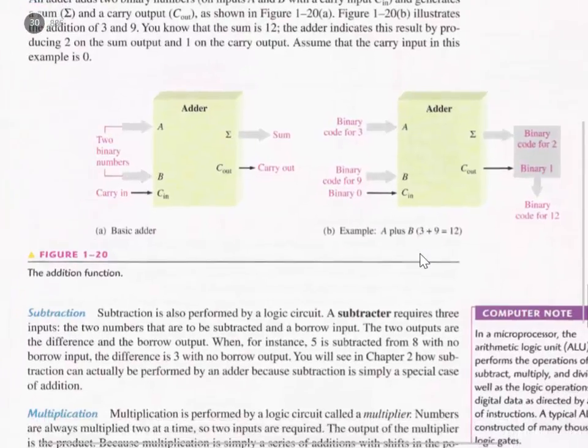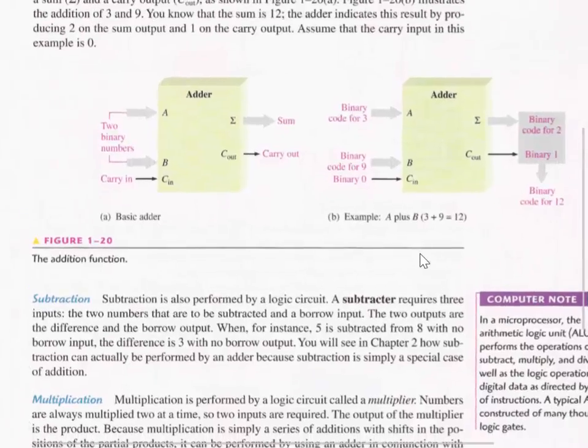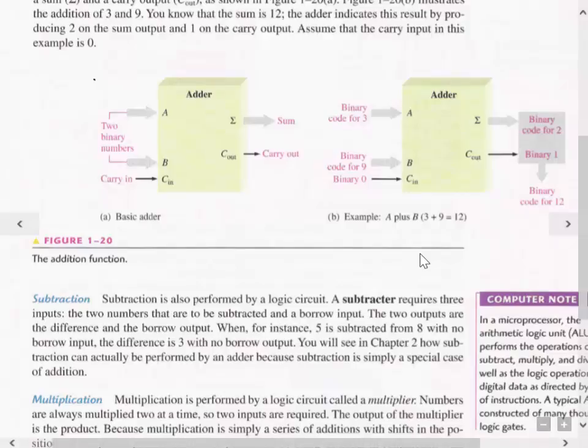We have multiple circuits there. We'll spend a lot of time talking about an adder. An adder has 2 numbers that go into it. We have not talked about how we add binary numbers yet, so it's a little early to get into that. But if we put in, say, 0, 1, 0, 1, and we put 0, 0, 1, 0, that's 5 and 2. We're going to get out 0, 1, 1, 1, which is 7, and we get no carry out in this particular case.